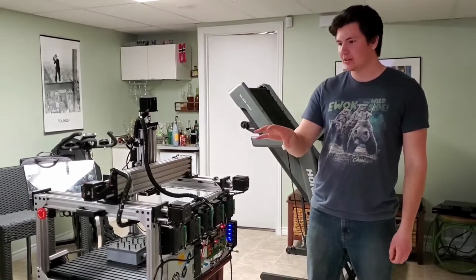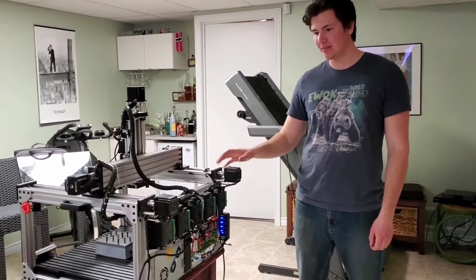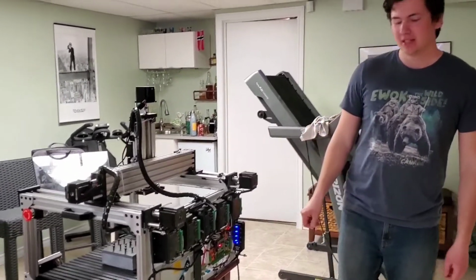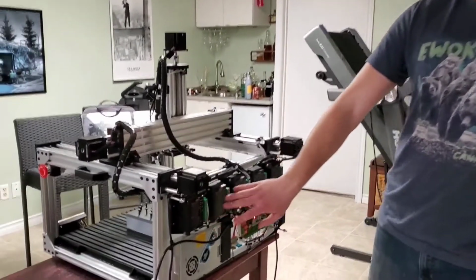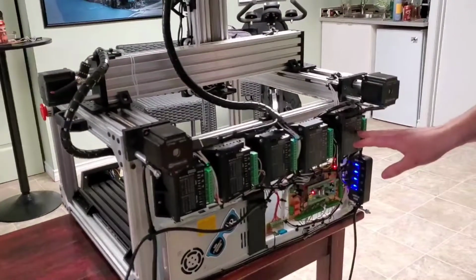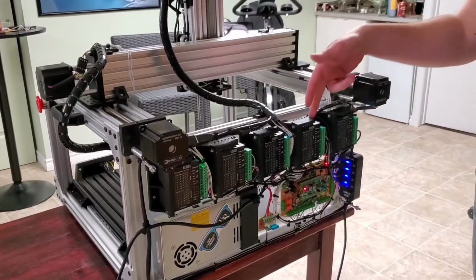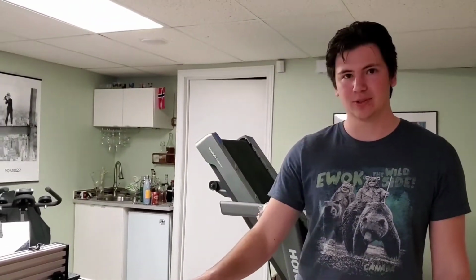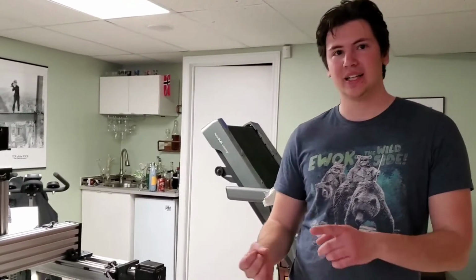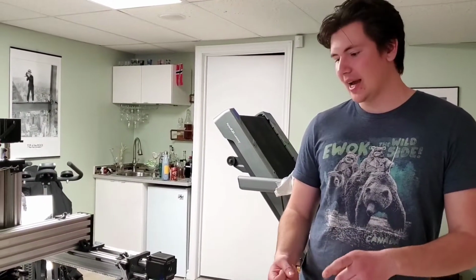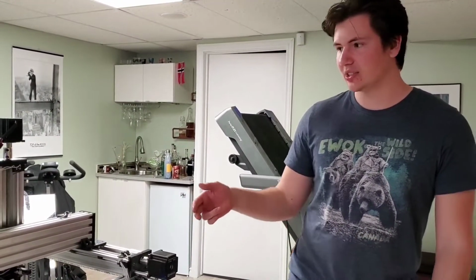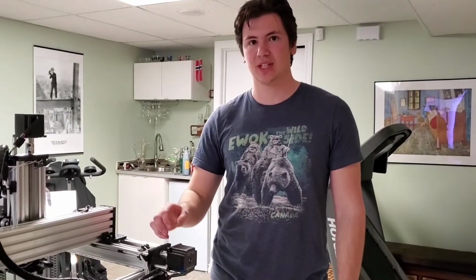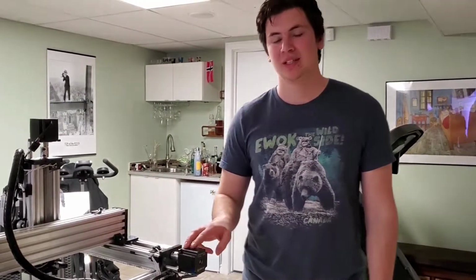So now I'm going to talk about a very important part of this machine, which is the motor driving subsystem. To start with, we had to select our stepper drivers back here. These had to be able to support the current from these motors, which is up to 3 amps. They had to have micro-stepping ability, and they had to be able to select the current, since we have different sized motors on here that have different current requirements.